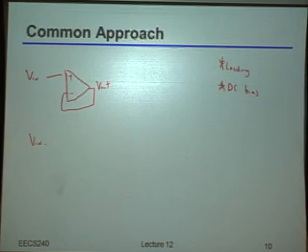So now, you guys tell me, what can I do to this unity gain buffer feedback circuit to basically hack it to try and solve both of those problems? And by the way, this is really a hack in the sense that this is only something you can do in SPICE and not in real life. But that's okay. We're just trying to use SPICE to actually estimate things that we really care about. Okay? So what's a hack you can do, for example, to make it so you can actually fix the DC bias, but still decouple the feedback from the input? What do you guys think?